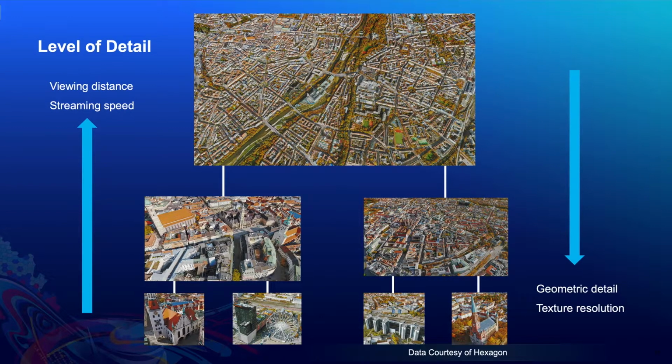And to put the data in the tree like that, and also create the transitions between the different levels fluently, so that the user does not notice that something changes in the model, that really is the challenge in creating this level of detail. But it is also something that's very much empowered and supported by what I3S is and represents, and also by all the algorithms that I3S supports. For example, the Draco compression really helps to create very small geometry in those mesh files.